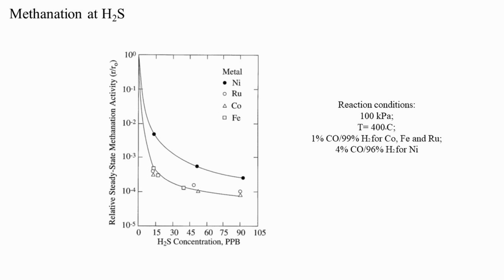Hydrogen sulfide chemisorbs dissociatively on nickel. The chemisorption process is reversible, and in principle sulfur should be removed in a hydrogen stream. However, the driving force is very small and decreases with decreased coverage. Sulfur may be removed by oxidation in steam. The exit gas shows the presence of sulfur dioxide as well as hydrogen sulfide.